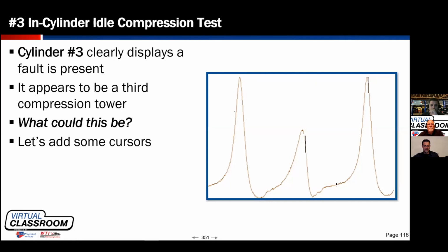I just want to make sure the guy got it. And if you think about the significance of the firing order, halfway through the firing order would be halfway between 0 and 720. That's 360. So if I got the first 3 cylinders and the second 3 cylinders, 360 is where my nose is, big nose. I just take the first 3 and switch it with the second 3.